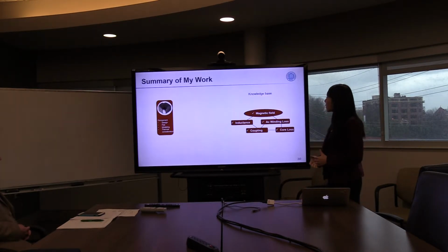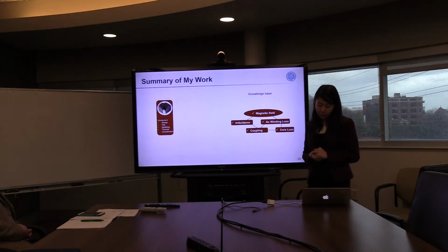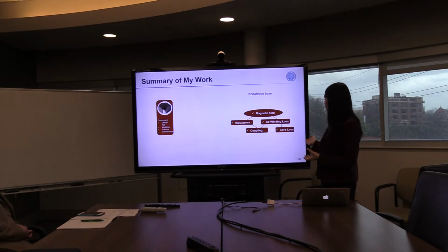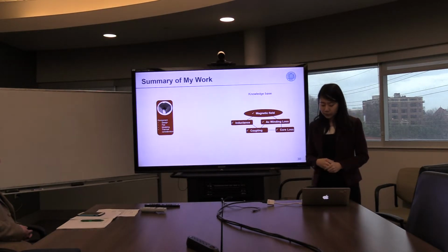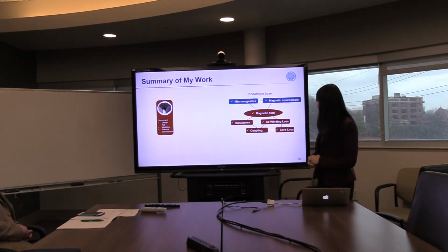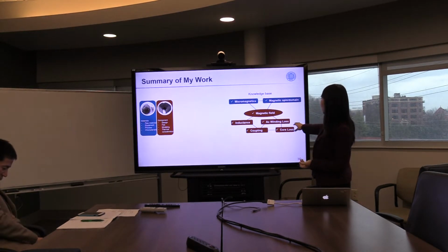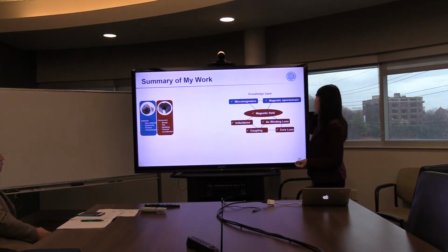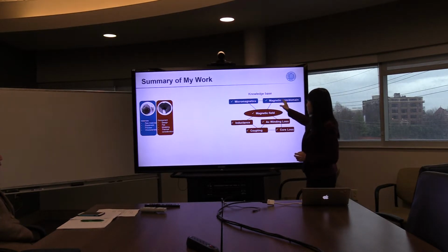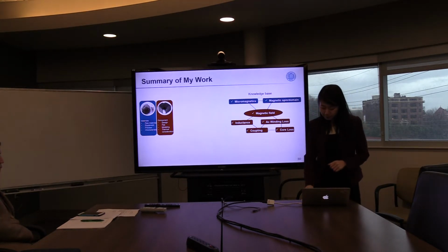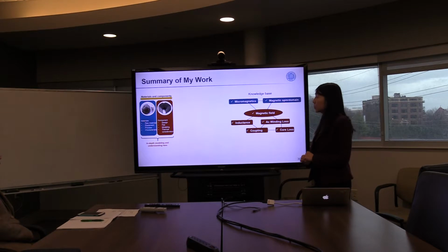To summarize my work, I start with component level modeling, including magnetic field, inductance, winding loss, core loss, etc. This is for behavioral modeling. And then I go to the material level to extend my knowledge to micromagnetics and magnetic spin models, so that they can be integrated into larger scale simulations. And this completes our understanding in the materials and the components level